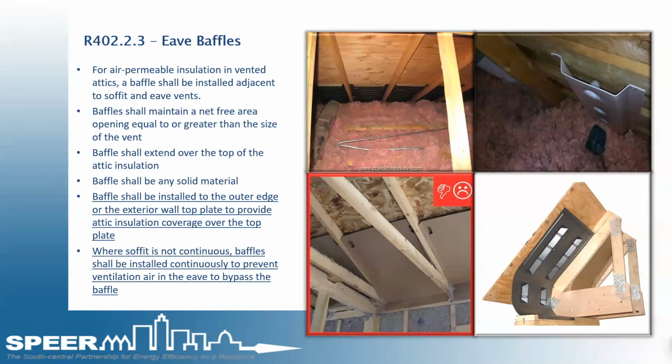A lot of times installers will just roll up a bat and stuff it in there over that baffle, and then keep that baffle in place by a rolled up piece of insulation, which is fine as long as the top plate itself is being insulated.